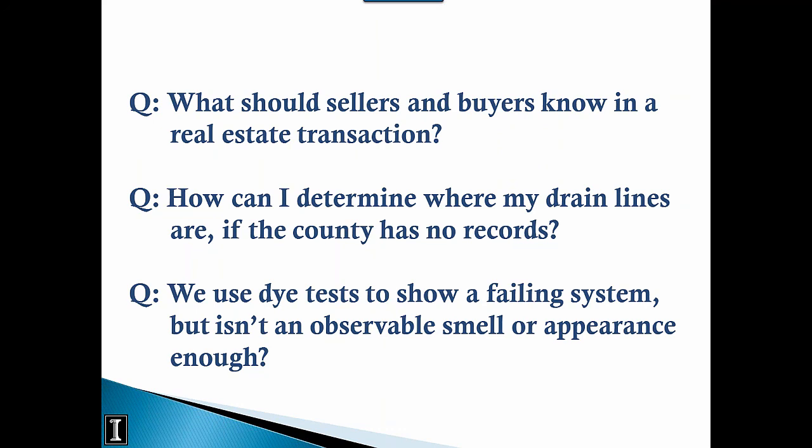as well as take a good look at that leach field, pull the records, make sure that they have the proper setbacks to the current code, to if there's a well present, the neighbor's wells, the neighbor's septic systems, wetlands, etc. So I definitely have them do the due diligence.